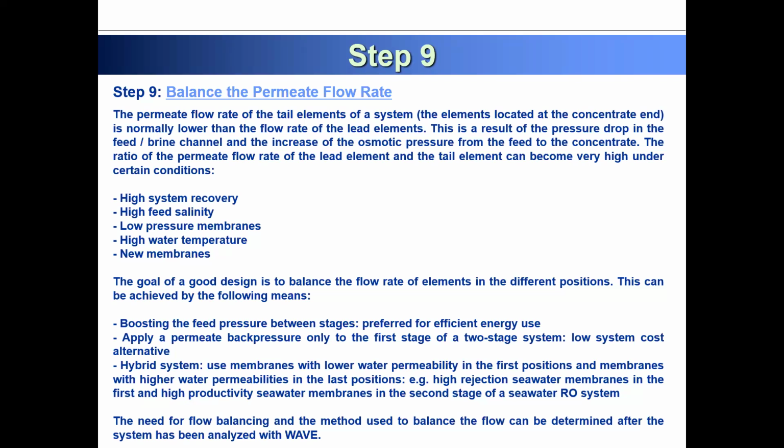It means the flow rate of the last element of the system, the element of the concentrate, is normally lower than the flow rate of the lead element. This is due to the difference of pressure in the feed channel and the increase of the osmotic pressure on the concentrate.